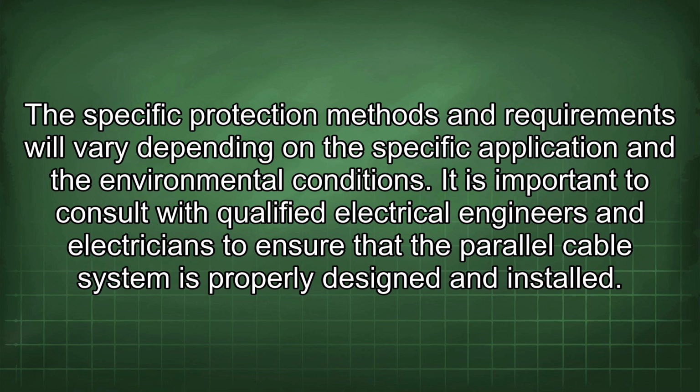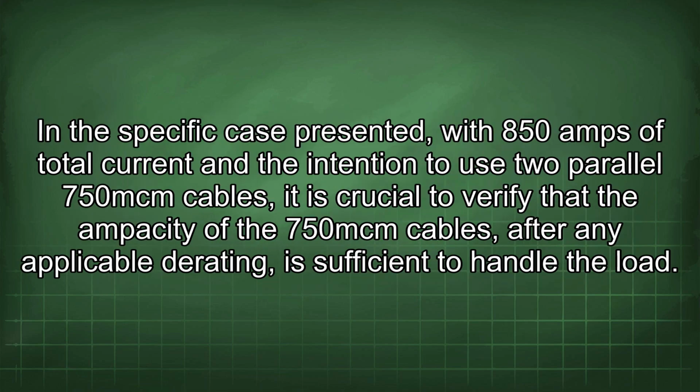designed and installed. In the specific case presented, with 850 amps of total current and the intention to use two parallel 750 kcmil cables, it is crucial to verify that the ampacity of the 750 kcmil cables, after any applicable derating, is sufficient to handle the load.